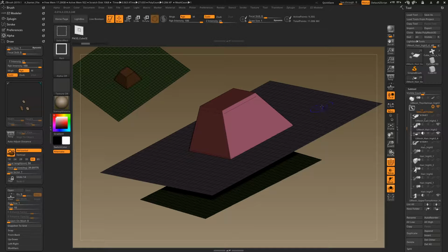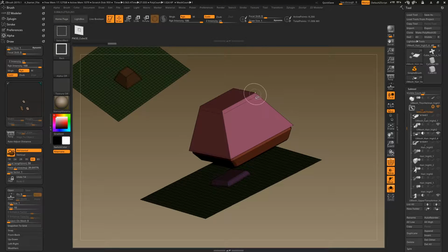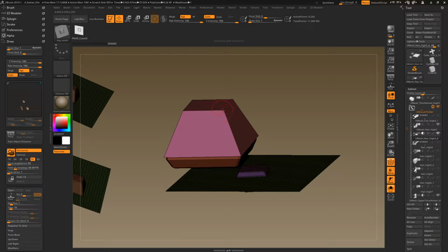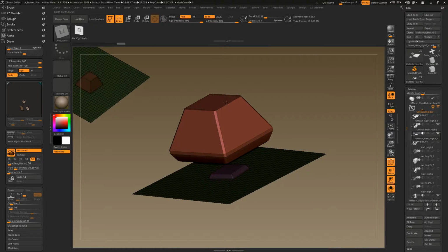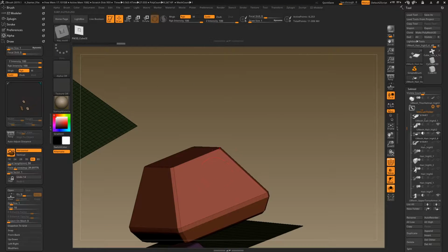They're made of 3 parts. There's the plane itself. There's the pink one, in this case the female. That's going to be a cutaway. That has to be hard edged. And then there's the male, and the male has got draft angles on it, which are surprisingly important and almost always overlooked.